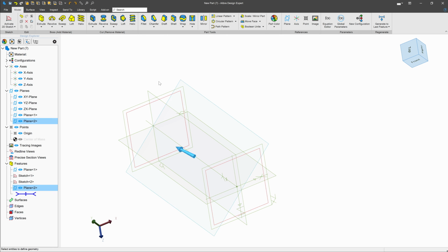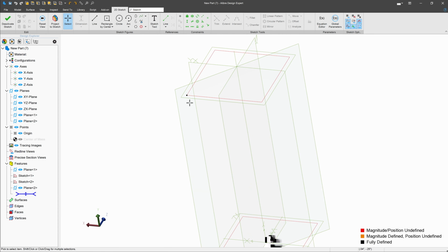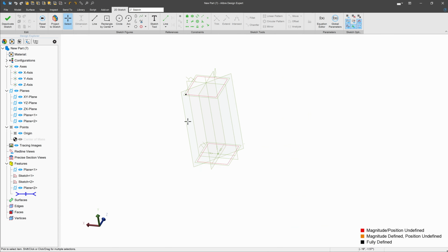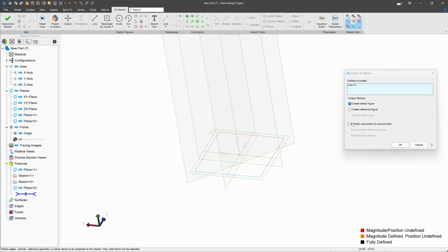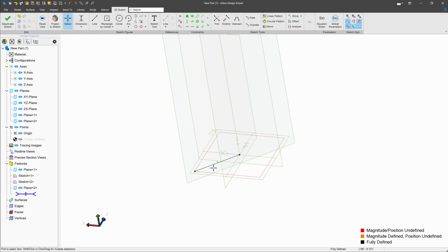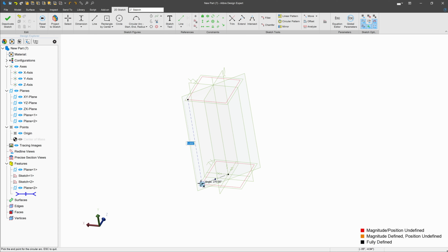And what I'll do is I'll create a sketch on this plane. And I've got my origin right at the corner. And so I'll import another line right here. Maintain association. Right? And actually I wanted that to be reference, so I'll right click and convert that to reference. And now I can import an arc. In fact, I'll choose start, end, and radius arc, just like that.